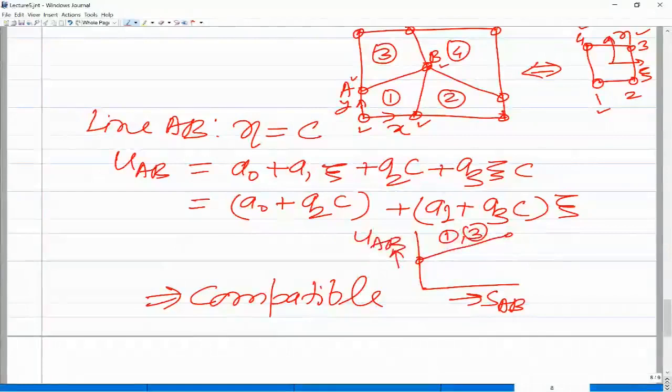But the advantage is that for the natural coordinates, when we finally evaluate the matrices, the Gauss quadrature numerical integration points are already available. Of course, we can always convert from there to any other coordinate of the same type. But the basic idea is that we should have a mapping to a square in the natural space, and as long as we do that, we will have a compatible element. Thank you, sir.